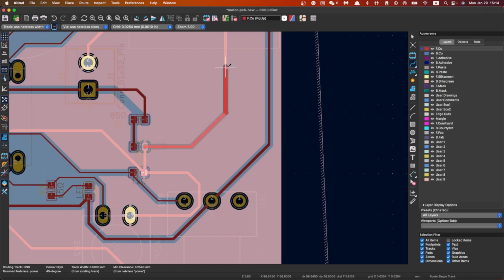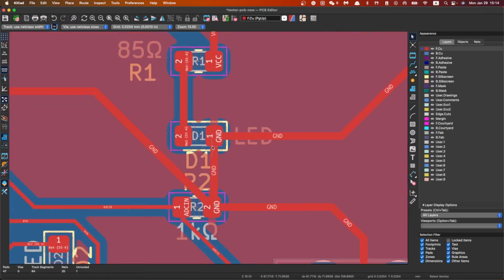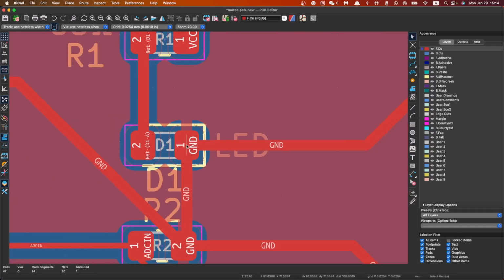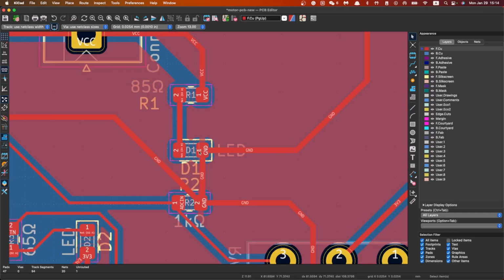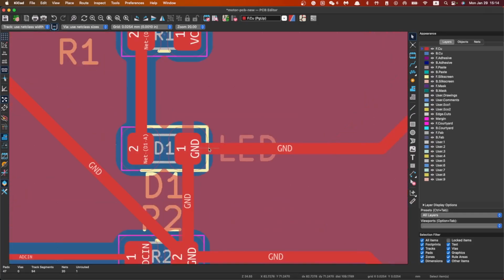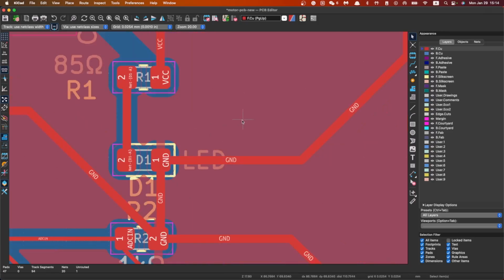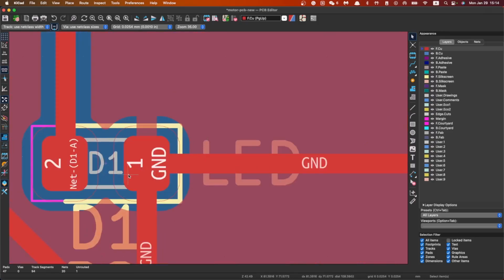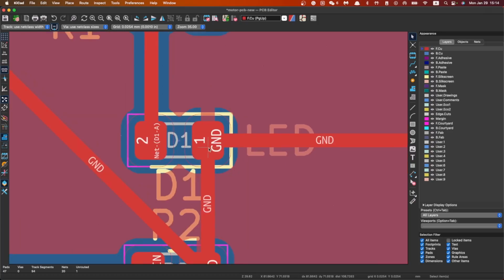Okay. So if it's like this, you can put the solder on either track if you want, right? And also this is a ground pin. So if you are messing around, making the solder connect all the way and make this pad connected to the ground plane, it's okay because it is just a ground pad. So it doesn't matter.